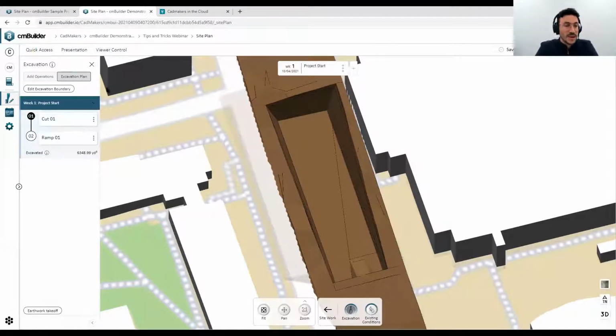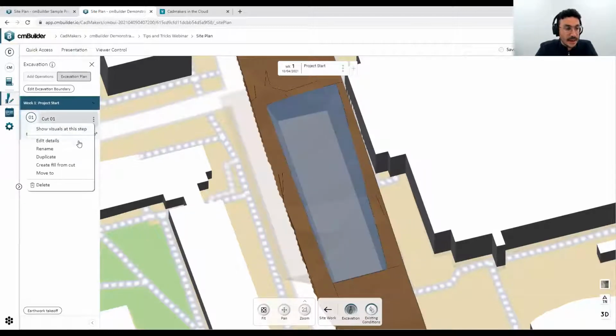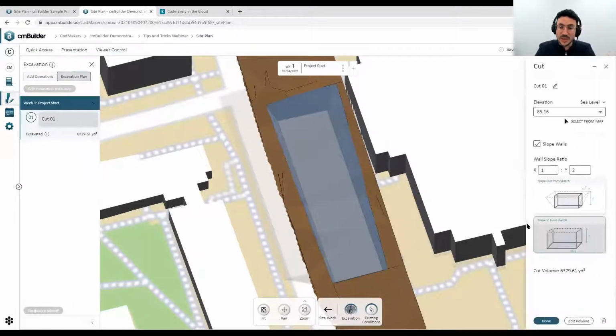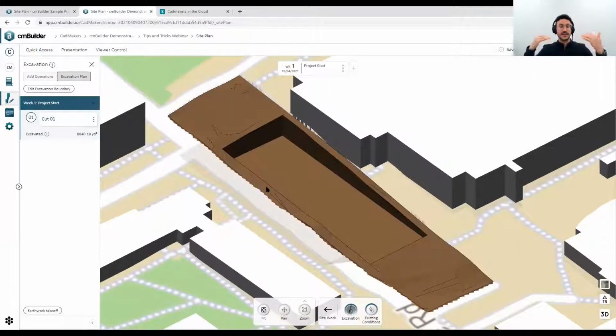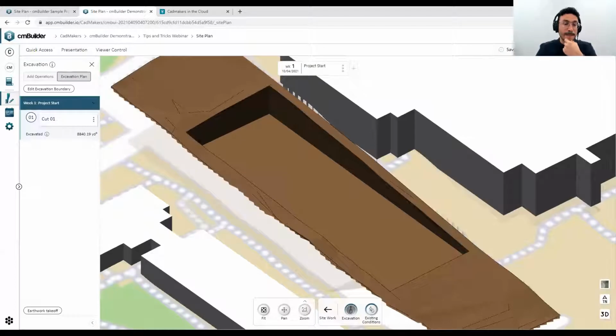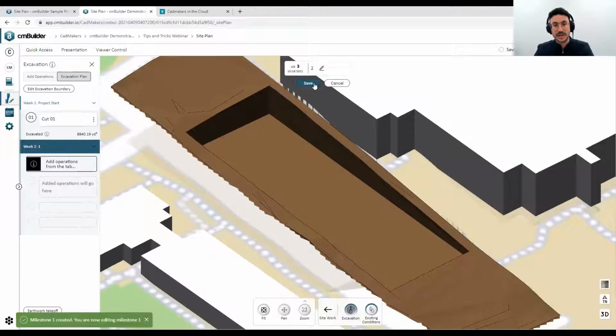Okay, cool. So last thing that I want to show about excavation is you can reuse the excavation shapes to represent different points in time for a shotcrete execution, for example, right? So let's say that you're going to create a shotcrete wall for this area over here, and you have to create several milestones to represent each one of these stages, right? So I'm going to create over here just a couple of milestones and just randomly naming them.